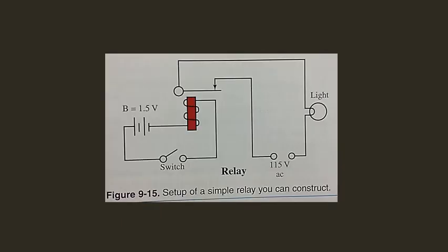The relay. The relay is a device used to control a large flow of current by means of a low voltage, low current circuit. A relay is a magnetic switch. When a relay's coil is magnetized, its attractive force pulls the lever arm, called an armature, toward the coil. The contact points on the armature will open or close depending on the normally at rest position.